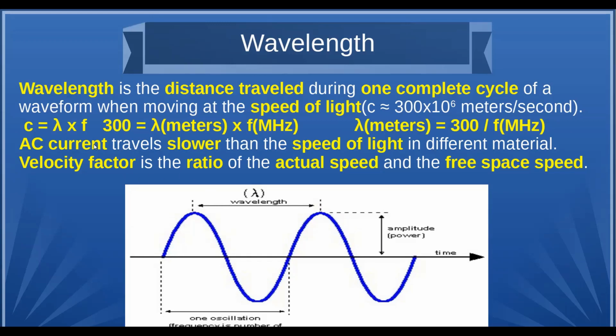In coaxial cable, sometimes it's as low as 0.75 of the speed of light. So you need that correction factor, or else your length measurement for the wavelength is off. And in fact, on one of the exam questions, you can get the right answer without doing the correction factor, but it'd be close enough that you can guess the right answer.